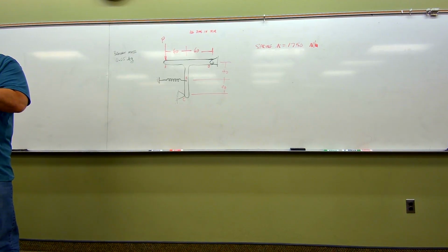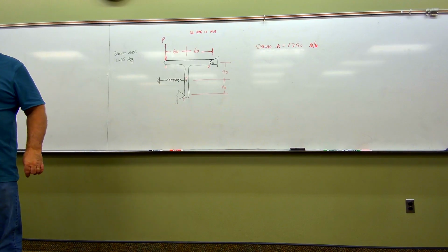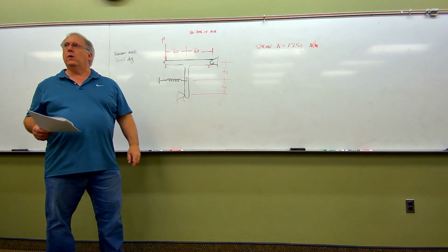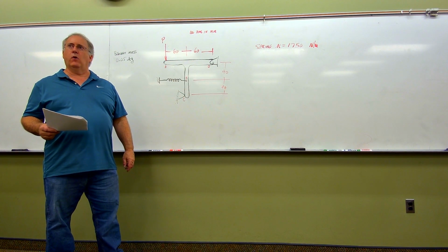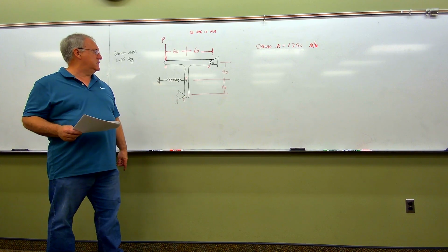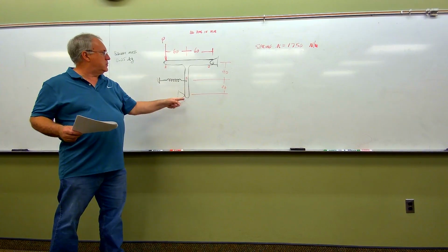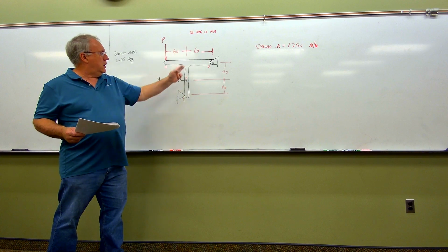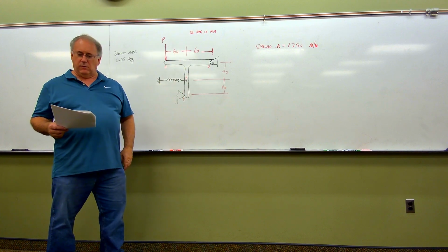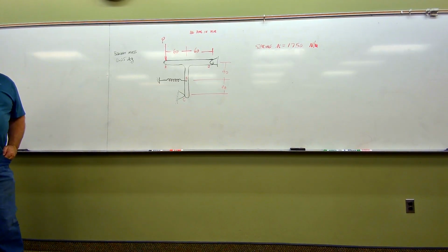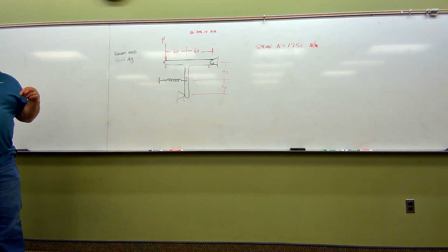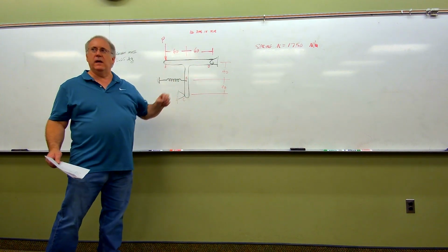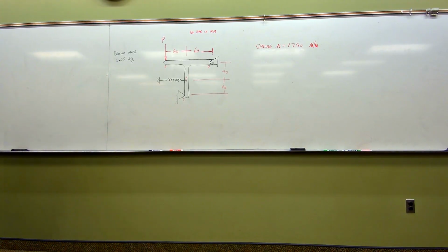I don't want to go into the ask here, but I want to stop right here and simply say, I've got a 0.05 kilogram body right here. By the way, we're not told anything about it being uniform, so in this case we have to make the assumption that it is. And if you look at this, we do have a line of symmetry right here, the pinhole notwithstanding, so you can treat this as though your line of symmetry is going right down the middle of this vertical piece right here. So the 0.05 kilogram body, linear spring, determine the force P required to break contact at C. We're going to do a free body diagram of this bracket right here. Take a moment, just sketch out what you think that should look like.